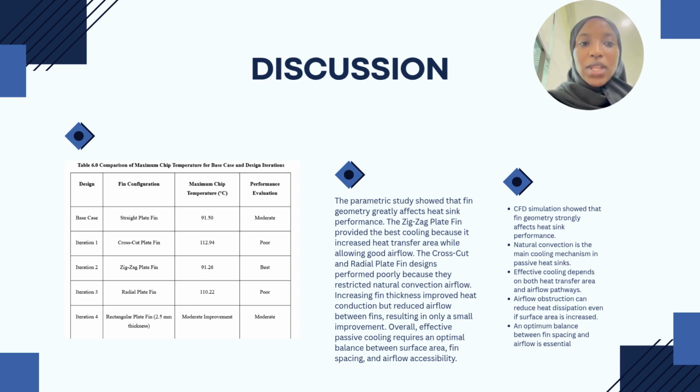Also, increasing the fin thickness improves the heat conduction but reduces the airflow between fins, resulting in only a small improvement in overall effectiveness. Passive cooling requires an optimal balance between surface area, fin spacing, and airflow